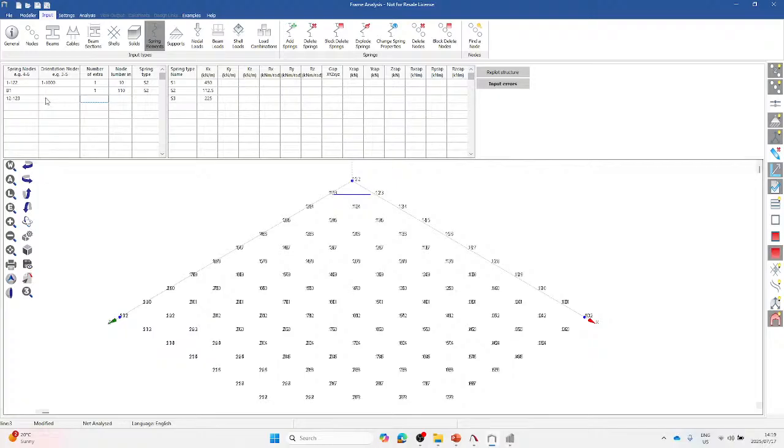And we need, sorry, I need to make sure I am doing the right thing. So let's say 202, which is this one. Let's create this one, sorry about that. And we're gonna have 1, 2, 3, 4, 5, 6, 7, 8 extra, so 8. And node increment should be 1, and then that should be S3 as the spring type.